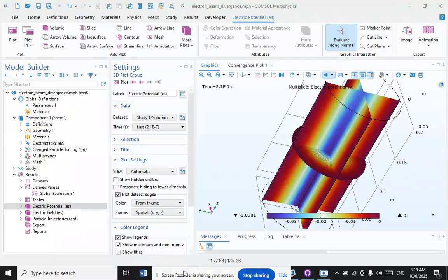Recently, this thermal fluid dynamics approach has been extended to multi-component substrates with an explicit treatment of the vaporization state transition per chemical species, permitting high fidelity simulation of the fusion and vaporization state transitions in alloys without the need to fit phenomenological recoil functions as is done elsewhere.